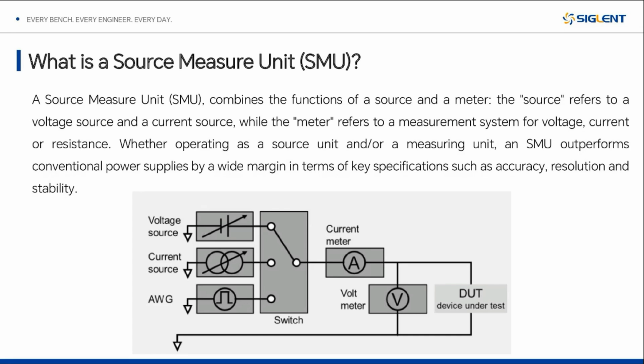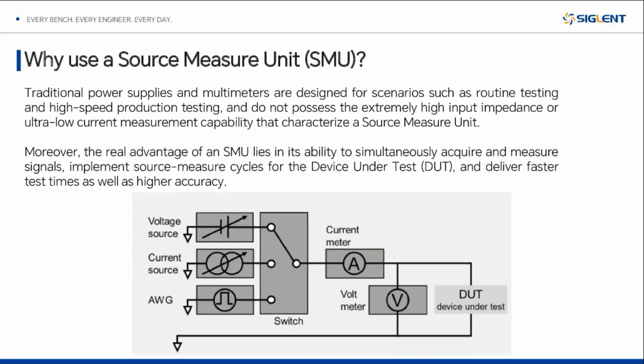Because of the way this system is integrated, it typically gives you a wide range of capabilities, especially as you talk about lower voltage and lower current measurements, higher current pulsing capabilities, some high voltage capabilities as well, and some high speed capabilities in both how we move that source around, like an arbitrary wave generator, and how we make those measurements and analyze the data. So in some sense, it's a combination of complex power supplies and measurement tools that integrate for accuracy, resolution, and stability.